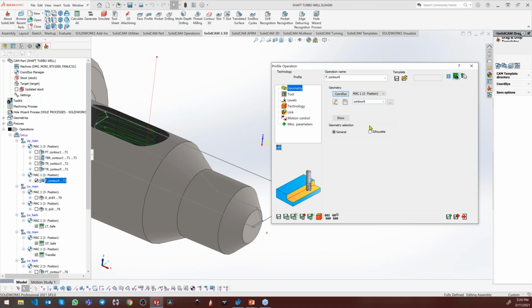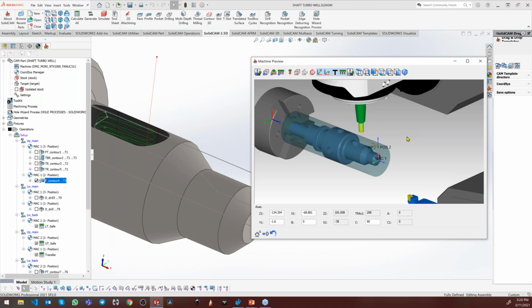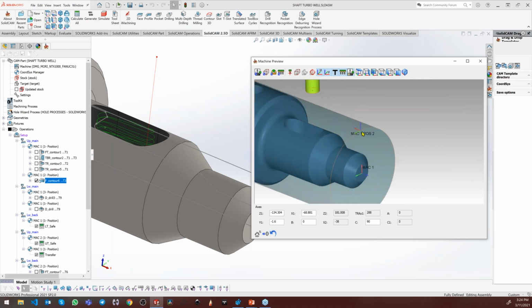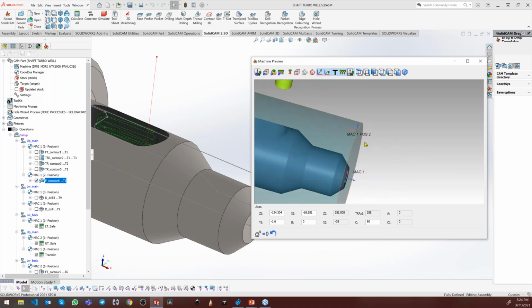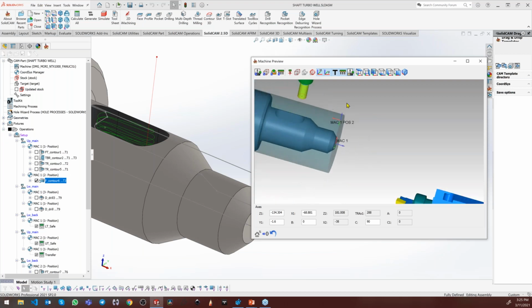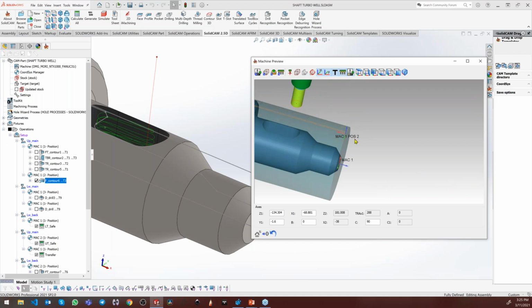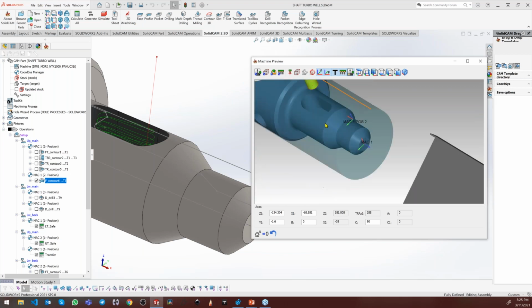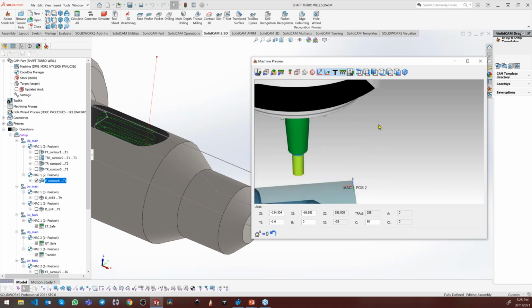But if you go to machine preview and press this button, you will now see also the X and Y orientation. This is the real orientation of your position that you will get on the machine after the plane rotation command. It's very important because in G-code you will get the start of the toolpath relative to the same coordinate system. So here I can see it will be close to 0 in Y, some big X and smaller Y, Z also positive.